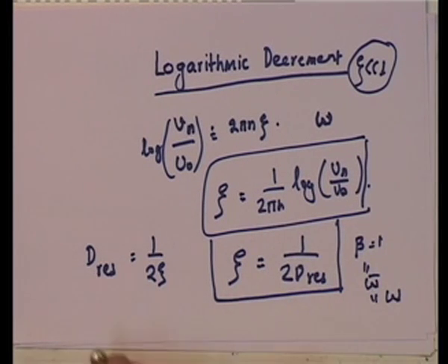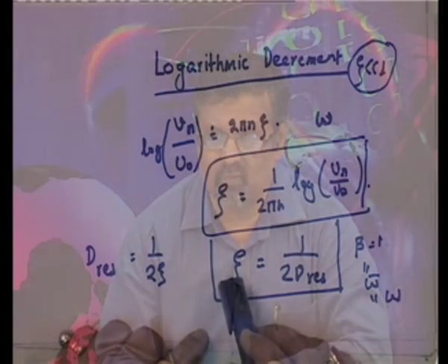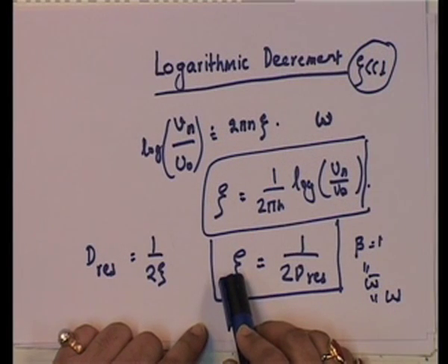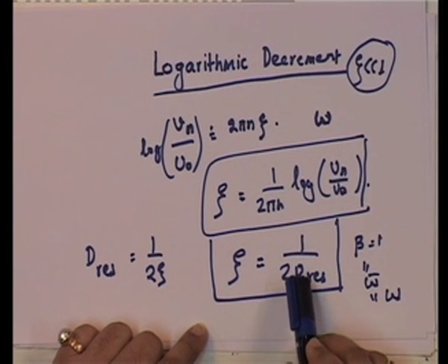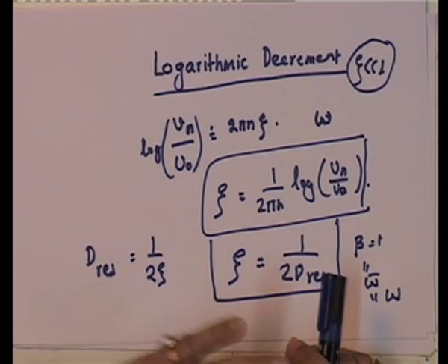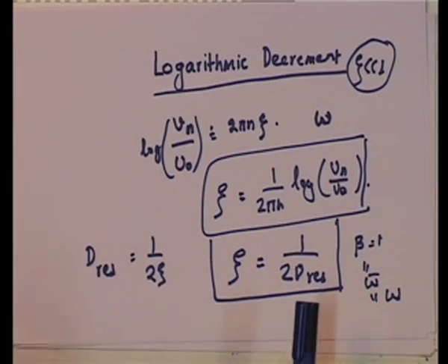The problem here is that in real life, when you have very small xi, the D becomes very, very large. When you have very large dynamic amplification and you are exciting a system, and it starts rotating, as you come close to this, you get a feedback into the system.